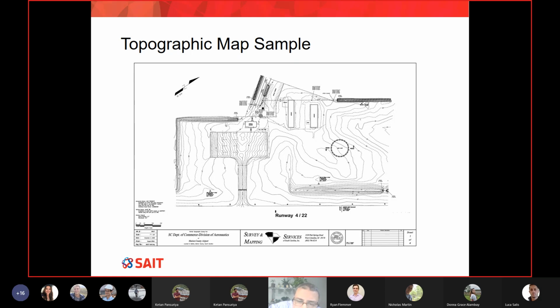Those features on site can be natural features, like rivers and lakes and other natural formations, or man-made, like a road and building and so on and so forth. Bottom line is, anything that exists on site, we need to survey, locate these points, and then place these points on a piece of paper. And remember, without a topographic map, I can tell you, you cannot build any project.